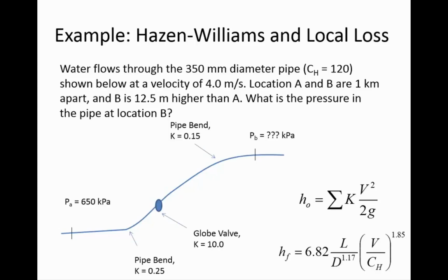It's a coefficient of some sort, definitely. It's the kinetic energy correction coefficient, and what it is related to is actually the velocity distribution. Again, what it means is that, let's say, for example, if you had laminar conditions, then the velocity profile is bullet-shaped like this. And if you use the average velocity in the velocity head term, when you have laminar conditions, then that would actually undercount how much energy is in the velocity head.